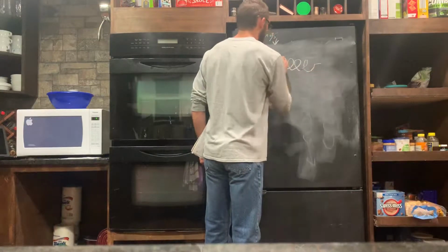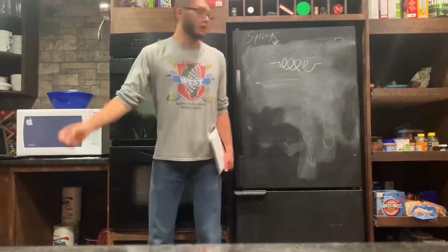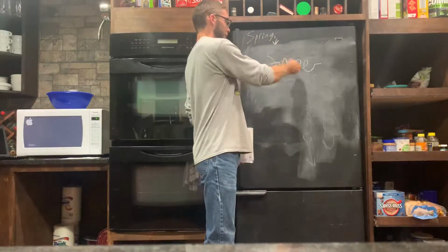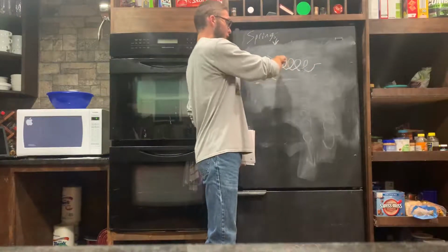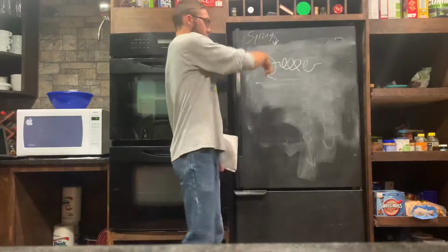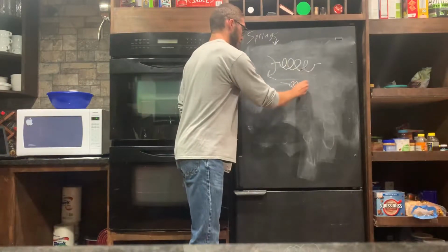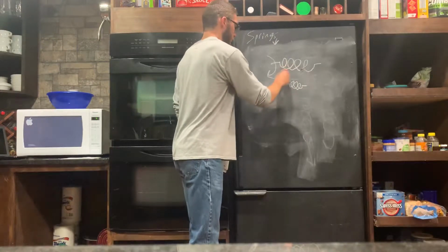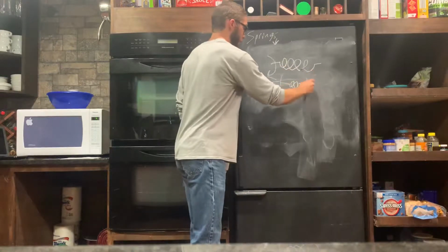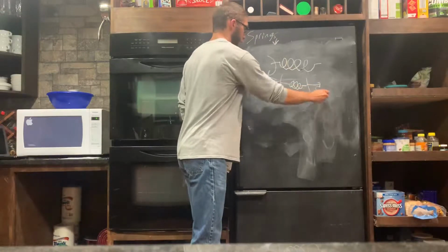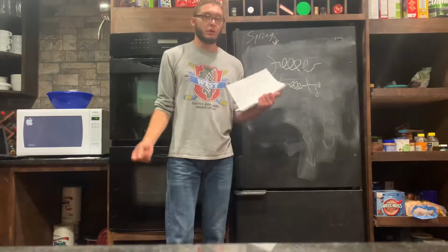This spring is going to have more of a torsional force, as we've talked about, and it's actually going to compress by rotating. In this case, since the force is that way, the spring will get a little shorter, and our deflection will be this and this distance, and we can add those together to determine the total deflection.